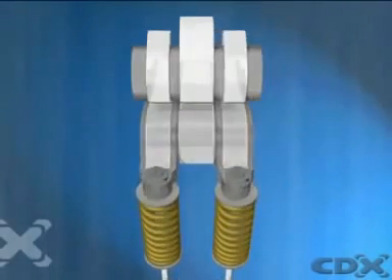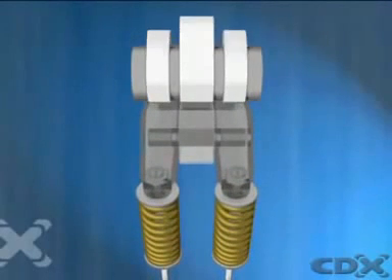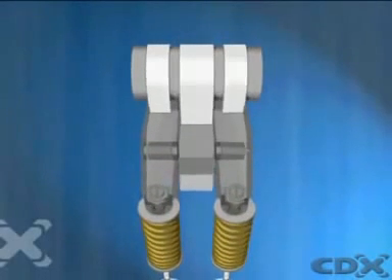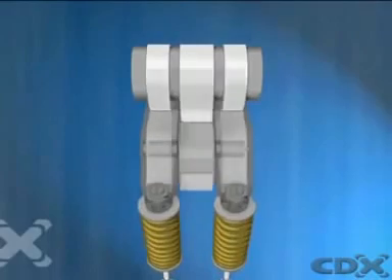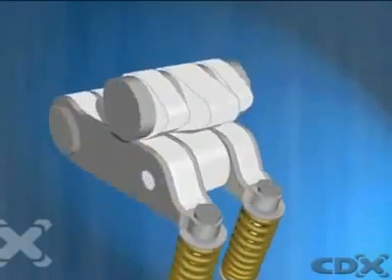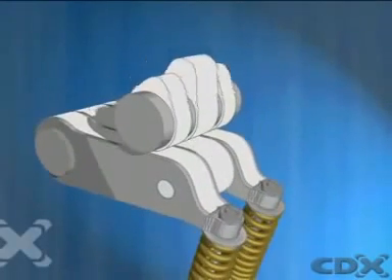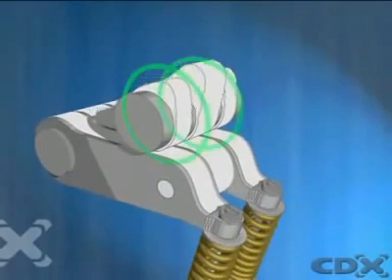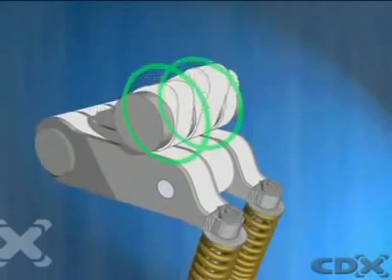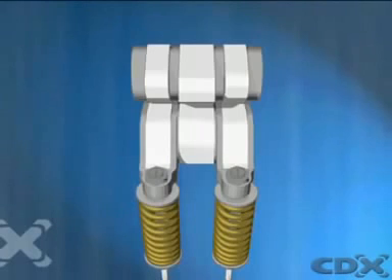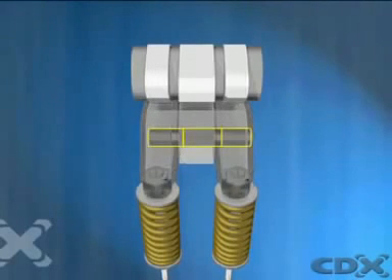When engine speeds fall below the threshold speed, oil pressure is removed from the pin and a spring deactivates the pin. The rocker arms are no longer locked together, and the valves are controlled by the less aggressive outer lobes. Cam changing VVT can also be used in a similar way to deactivate a second intake valve at low engine speeds, increasing the velocity and swirl of the air-fuel mixture as it enters the combustion chamber.